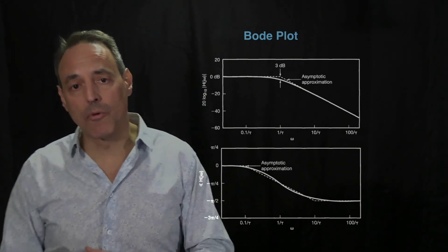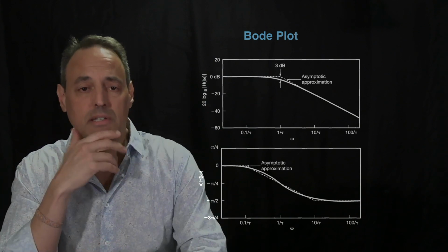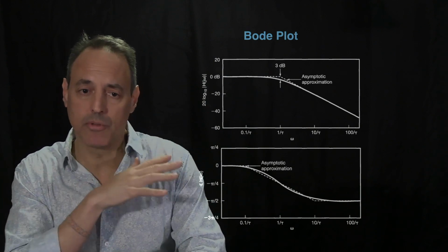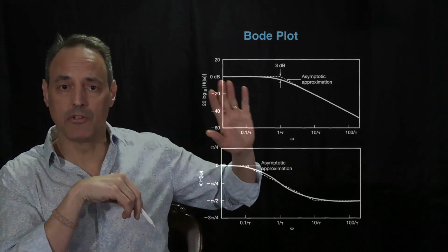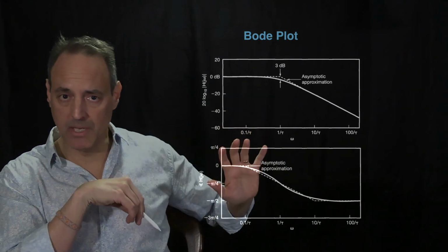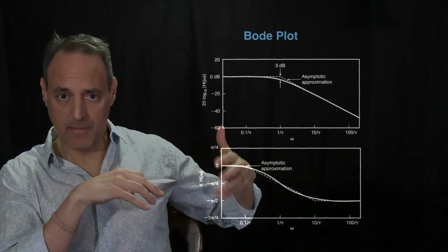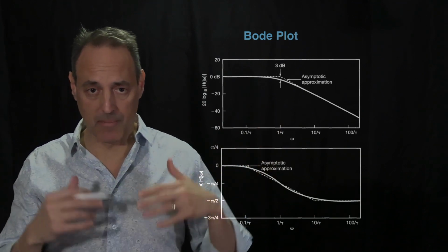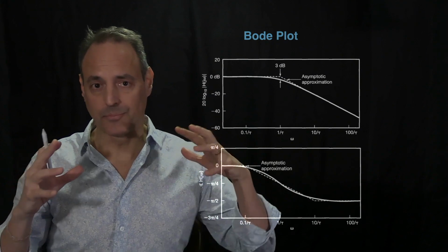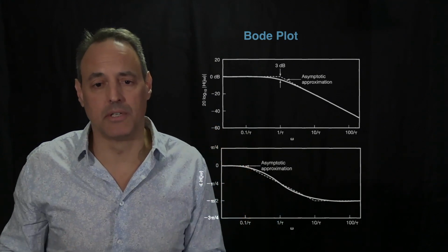So part of what a Bode plot does is, if you're processing a signal through a system, if you can produce a Bode plot, it's telling you what's going on in terms of a filter plus the phase content. And these two pieces are the critical pieces you need to manipulate a signal to a desired output. So the Bode plot becomes essentially a core characterization of signal processing and signal processing design. So keep that in mind. You'll see lots of Bode plots in signal processing overall because they're a very intuitive way to start thinking about how the shaping of signals is happening as a function of frequency, both in terms of the intensity and phase in the Fourier domain.